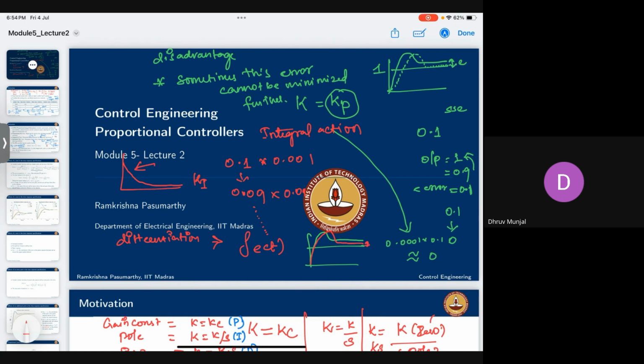Instead of changing it simultaneously, we are making a history of errors. We are saving the history of error and how well the error is going down. If you multiply a KP, you don't know whether the error is getting increased or decreased. You don't keep track of it if you are not saving or visualizing it. So this KI term will keep track of those errors. It will integrate those errors over a period of time, then it will change the gain accordingly so that you can see an exponential decrease of the error.